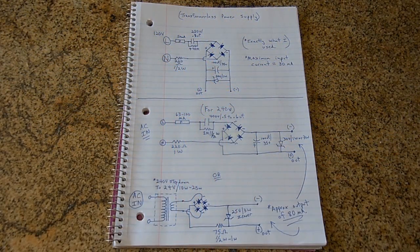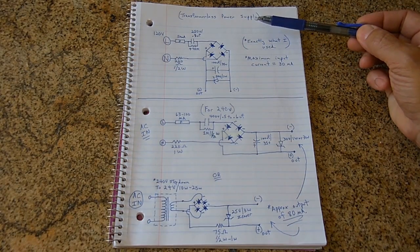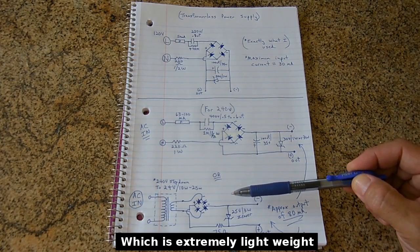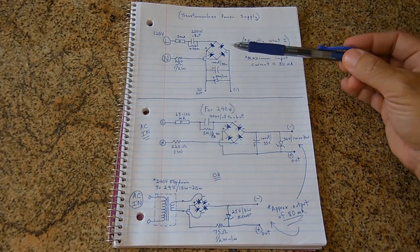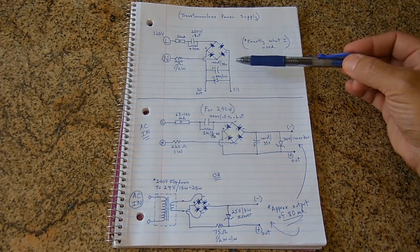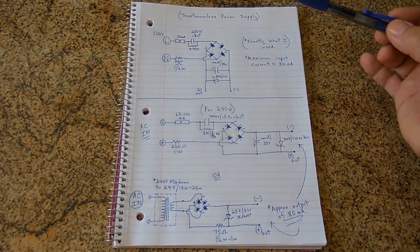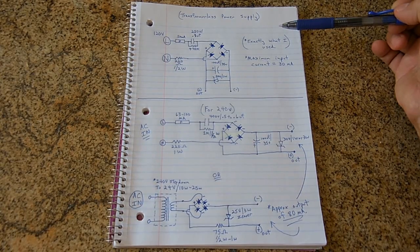Now I'm going to show you the circuit that I put together to drive the LED strip light. I'm going to be showing you a few different ways to power your strip. The top is 120 volts using a transformerless power supply, and below is for 240 volts showing a step-down transformer or a transformerless power supply. This is exactly what I used in my LED strip. Keep in mind I use this with 3 groups of 8 instead of 4. So I'm going to show you one change you're going to have to make to be able to use this for all 4 groups of 8, which is 32 LED chips.